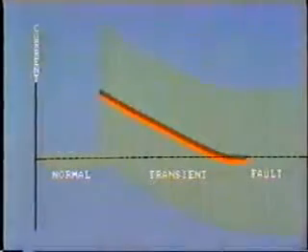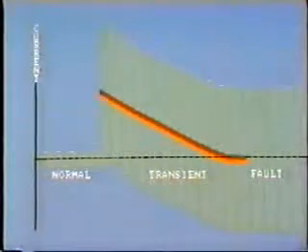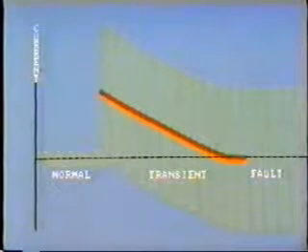However, there is yet another factor to make matters worse. Between normal current flow and stable fault current flow, a transient is created like this for perhaps 15 to 20 cycles. The amplitude of the current wave is the same as the stable fault current, but the whole sine wave has been raised as though a declining DC current has been injected into the circuit.